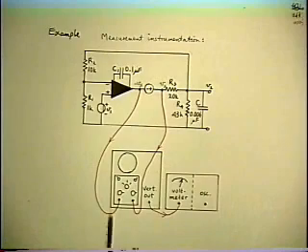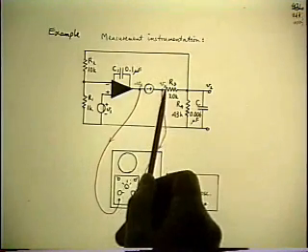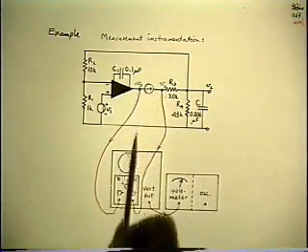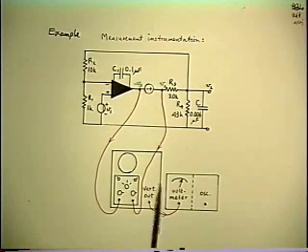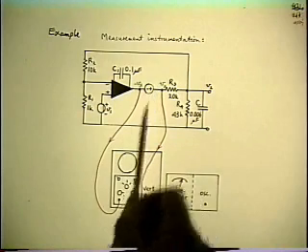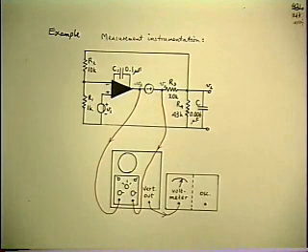But anyway, you remember that it exists. And so that's what you can do in this case. So for each frequency, you measure the magnitude of Vx and the magnitude of Vy and the magnitude of Vz. And you plug into that formula and you find the corresponding phase angle of the loop gain at that frequency.